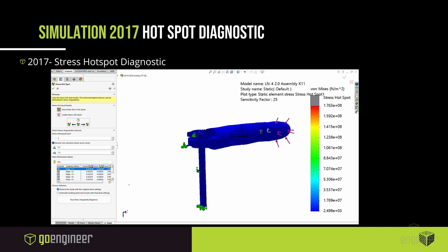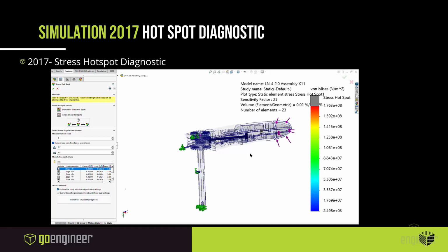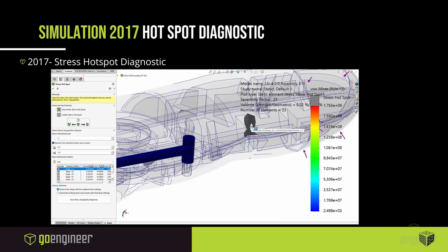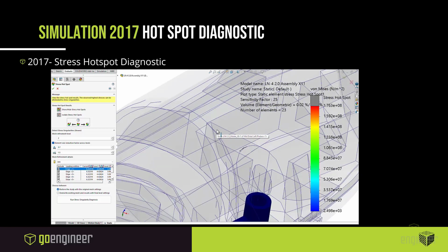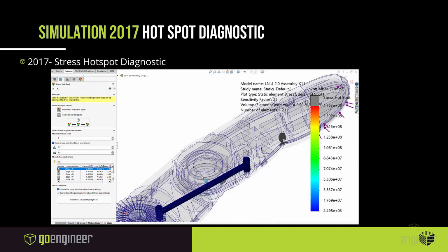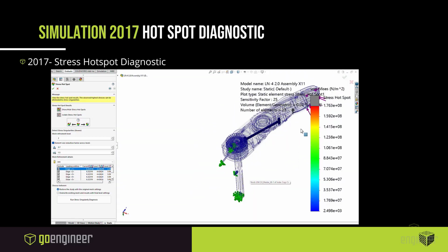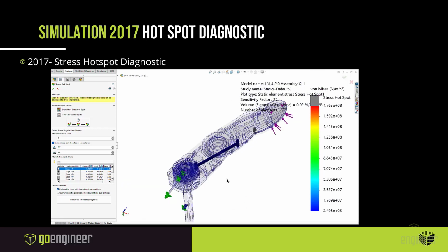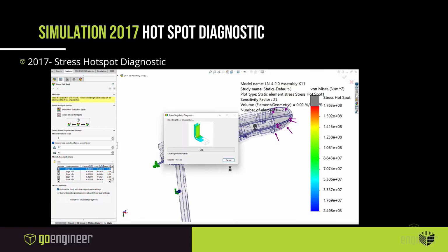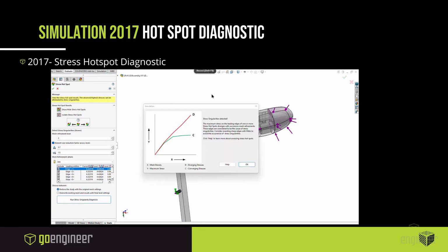On the left, there are some edges where it tells you which edge is exhibiting bad meshing or bad elements. If we isolate the areas that yield bad elements and meshes, this is a great way for us to analyze what's going on within the model, where the mesh nodes and elements are. And I chose to show this area because I was going to be looking through the rest of the model, and I was kind of curious to see what's going on in particular regions of the model. So you see I'm looking here, trying to get a good view of where the elements are bad, which elements are going to yield really wonky results. And it's nice that SOLIDWORKS gives us a transparency of this.